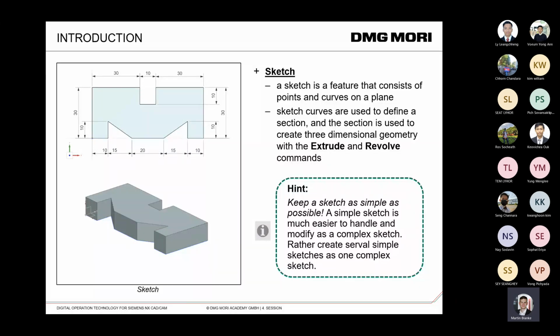So on the right side, you can see my personal hint. So keep a sketch as simple as possible. A simple sketch is much easier to handle and to modify than a complex sketch. Rather create several simple sketches than one complex sketch. So this is my personal hint for you.